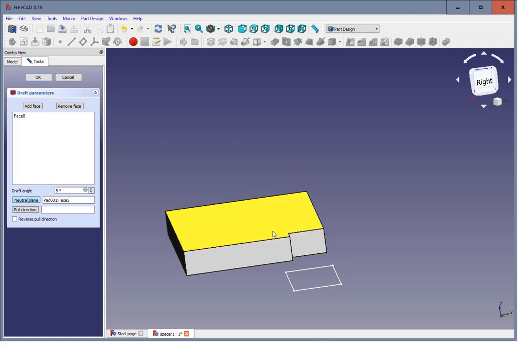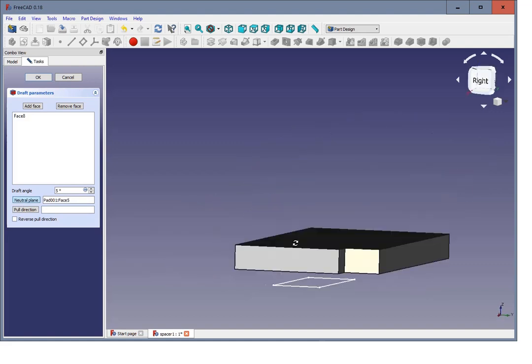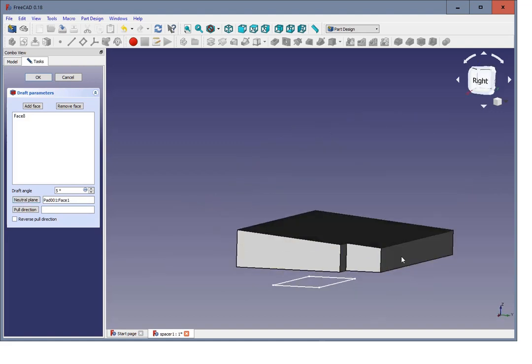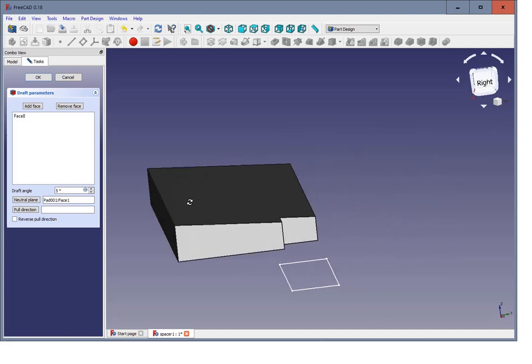But that's not what we actually want, because I measured the whole thickness and that was here. Now unfortunately it goes upwards instead of downwards, so what we have to change is the pull direction, and it goes downward. You could also change where it pulls to if it wouldn't be a move just in the Z direction.